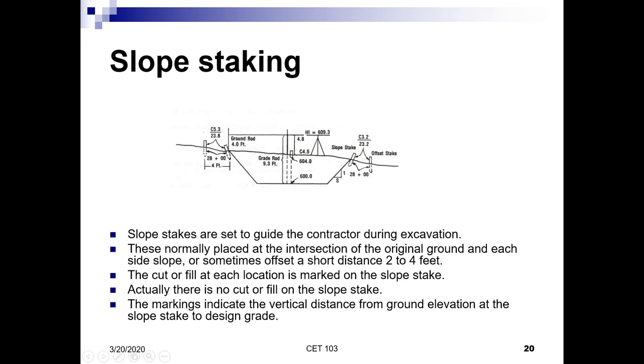We would like to know the whole distance, which is usually given to you in the construction documents. Then from there, we would decide whether or not we're going to be at a halfway point of that, which in this situation would be half of the roadway. Then we would also need to know the slope ratio of this line, which is usually given in the construction documents.